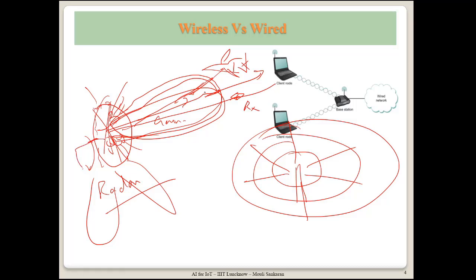So the gain pattern is the same for both transmission and reception. The maximum signal is transmitted in this direction, and when the reflected signal comes or another device is transmitting, the majority of the received signal will be received in this direction. Whereas if any signal is coming in this direction, it will not be received because it will be attenuated. Side lobes, or less gain on this side, is attenuation of the signal.